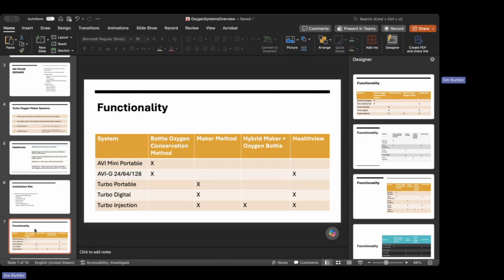That's due to the fact that above 18,000 feet, the time of useful consciousness is a mere 3 minutes. That means you have to detect the problem, resolve the problem, and be able to descend to an altitude that's safe for flight without oxygen, all in 3 minutes. It's virtually impossible to do that without proper backup equipment and training.